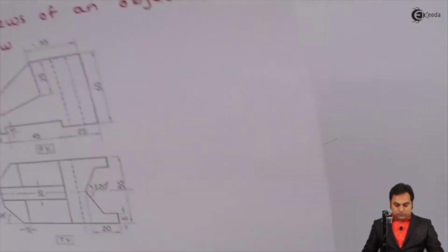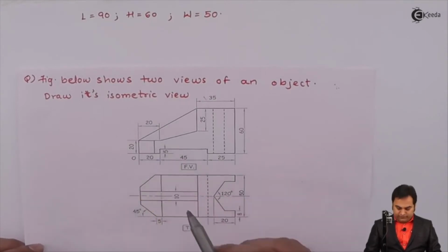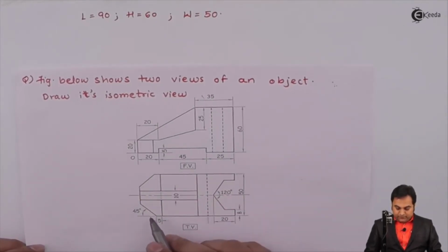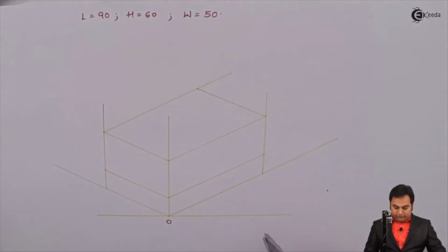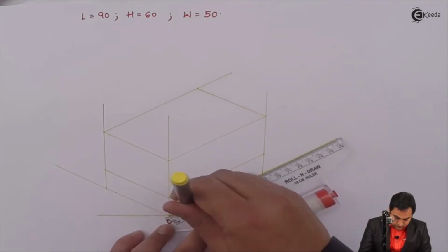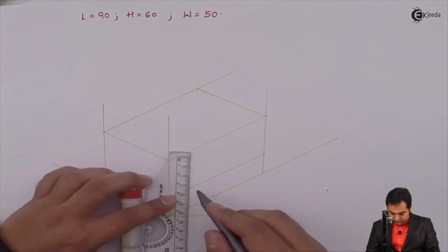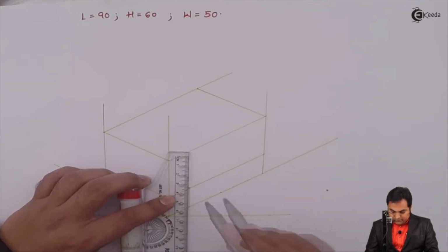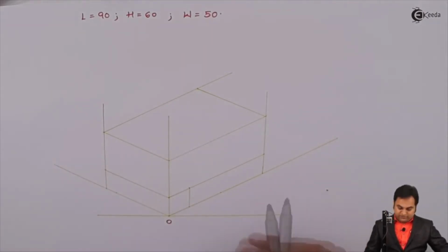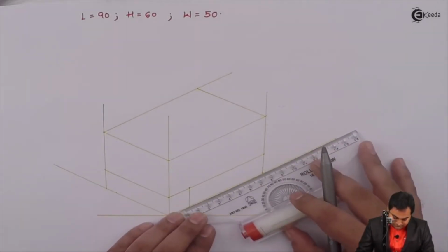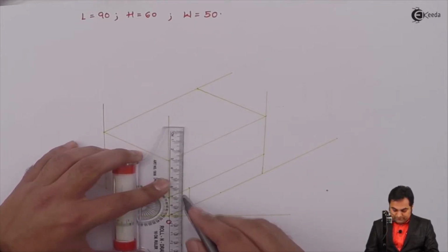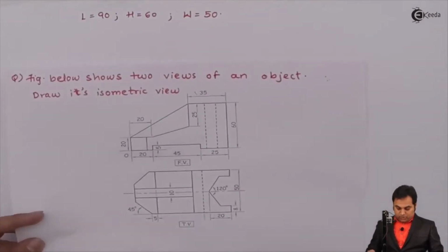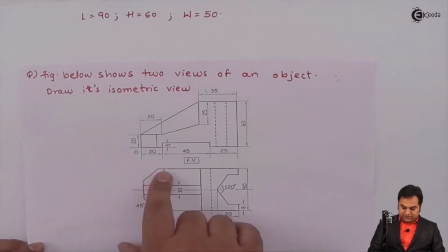Next, when we look at this surface, there is a change of plane between both of them, and it is visible from the top view that after taking a distance of 20 mm length, up to 5 mm, this plate is there. So I'll take a length of 20 mm. Drawing a light perpendicular line. Next, after this I'll measure 5 mm from here and then draw a light parallel line. Next, looking from the top, this object has such a shape.